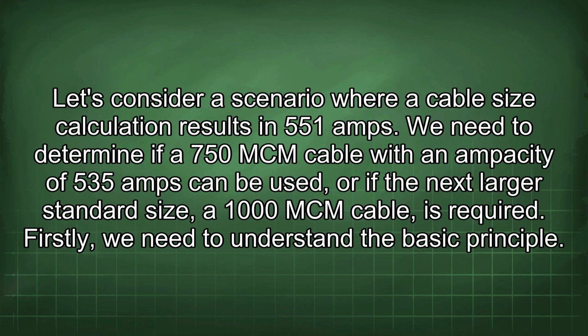Let's consider a scenario where a cable size calculation results in 551 amps. We need to determine if a 750 MCM cable with an ampacity of 535 amps can be used, or if the next largest standard size, a 1000 MCM cable, is required.